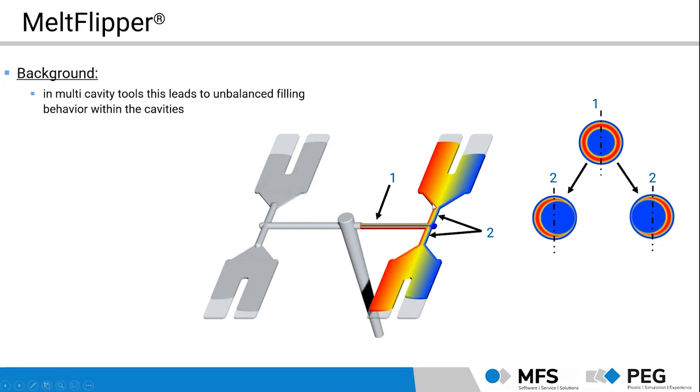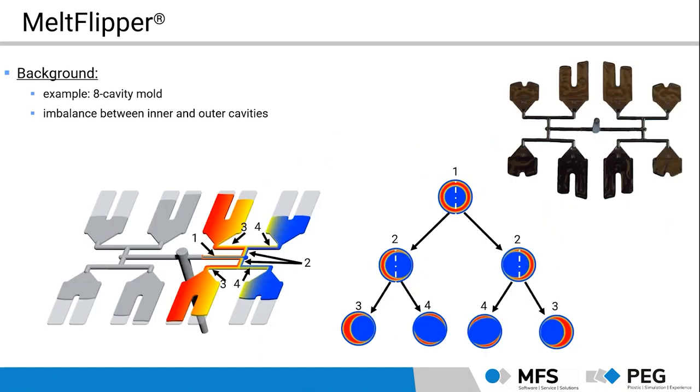You have the higher sheared material on the inside here, so this flows into the inner area of the cavity, and we have the lower sheared material, so the colder, slower flowing material here on the outside of the cavity. So we have different temperatures. We have a temperature distribution which is not equal over our cavity. And we have also a different filling speed.